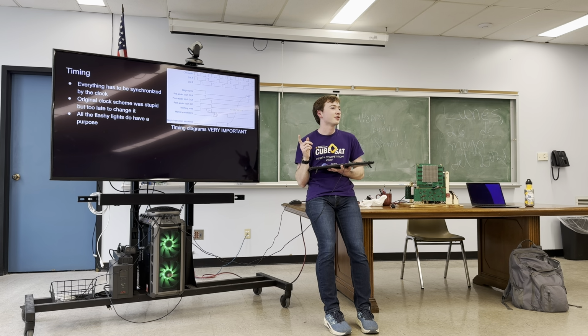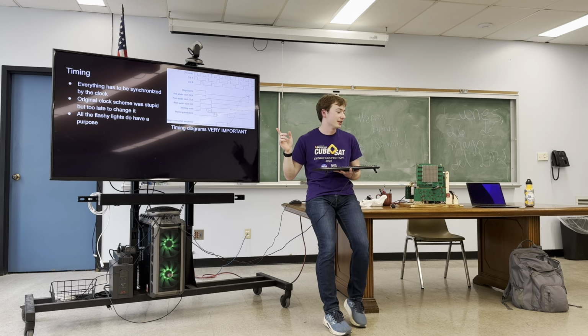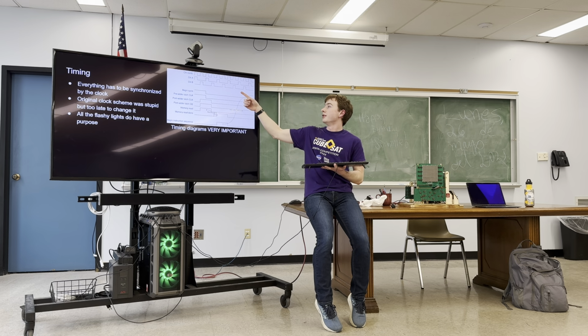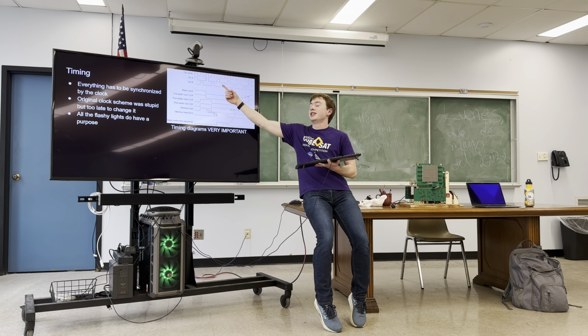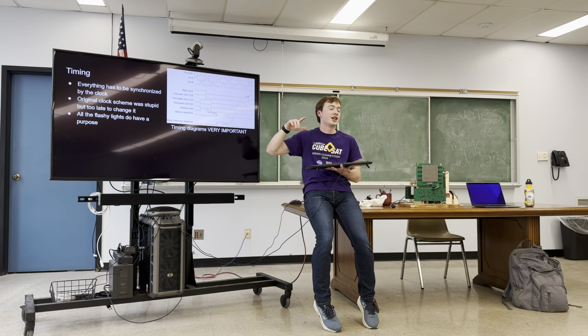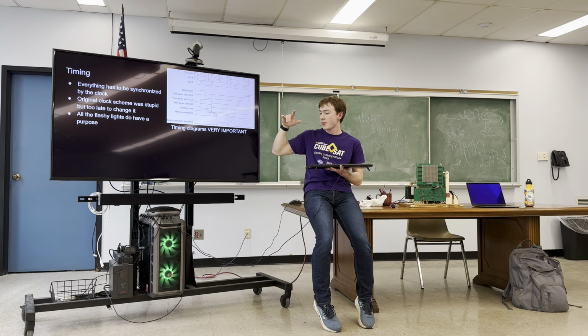And also, last year when I was thinking about really basic stuff, how to build it, I thought it would be cool to have 2 different clock signals that look like that. And so the idea was to avoid race conditions where data changes at the same time as the clock changes.